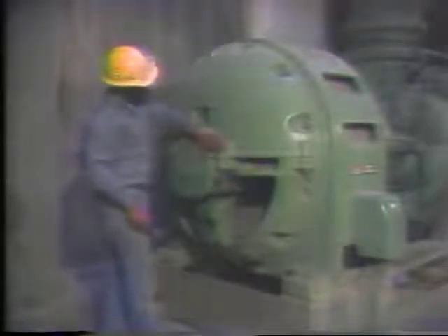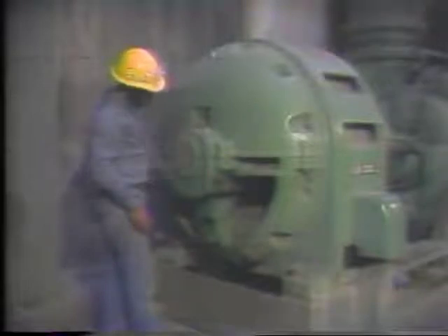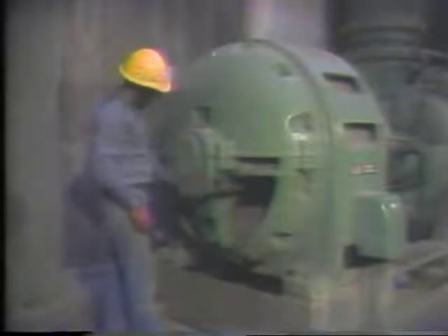There are a variety of ways to check the temperature of a bearing. The easiest method is to read the temperature directly from a temperature indicator on the bearing. However, most bearings don't have temperature indicators, and it's necessary to use another method. A common approach is to feel the bearing housing with your hand. This may sound somewhat crude and unscientific. However, with experience, you'll be able to tell quite accurately if a bearing is running too hot. Remember, however, that this test is only for the housing temperature and not the actual temperature of the bearing.